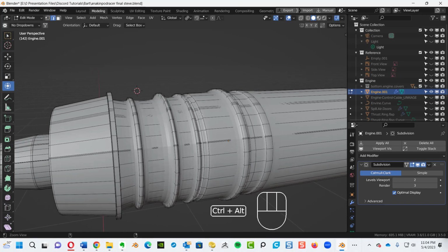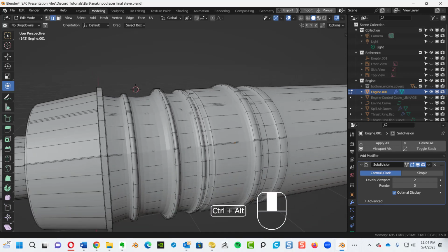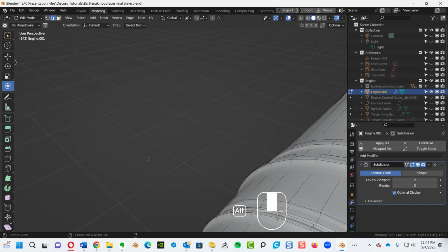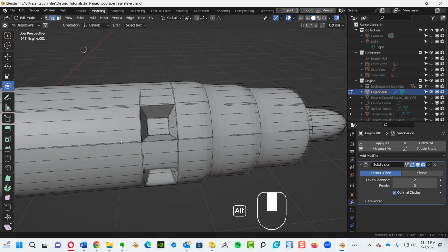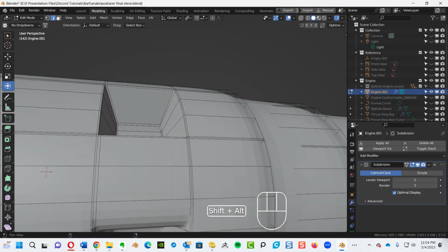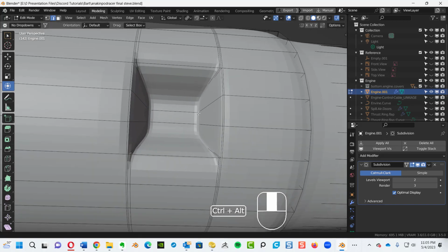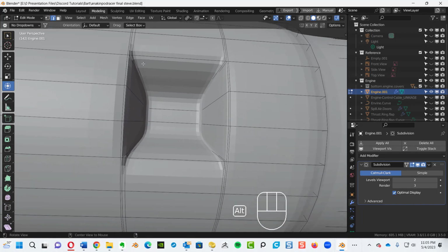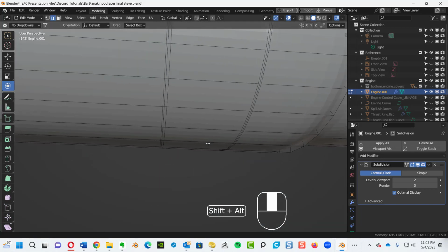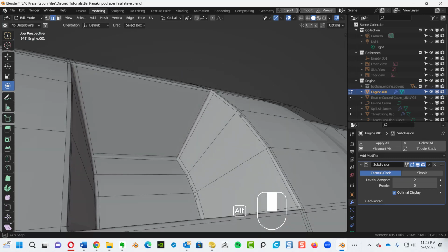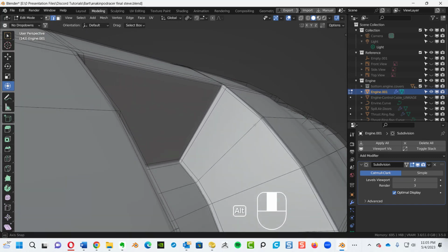You can see how it's rounded off, with the exception of these edge loops that I've added on there, and the same thing here. Okay, the others I kept open just so that you can see the difference. So no edge loops around the edges on these others, but edge loops here. All right, and that gave you a nice little clean edge.